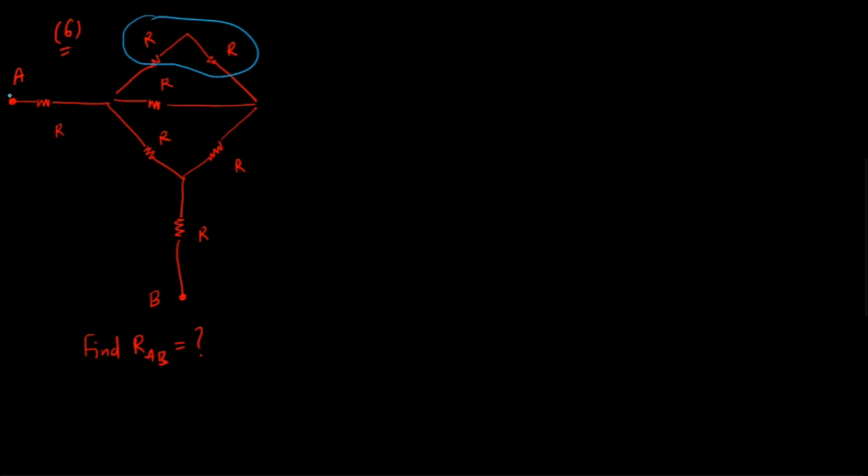So we have to find resistance between A and B point. So again, you can just draw the current through the wires and see how the current breaks. This will also let you understand what resistance is in which combination with which other resistance. So here you can see that there is no break. So these two resistances will be in series. So it is going to be 2R.